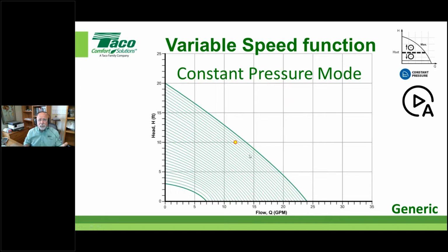The hop up is nothing more than what a standard single fixed speed application does. If you remember sitting through pump class 101, you understand as resistance increases, it goes from the right and up to the left. So that little hop is that initial feel of the zone valve closing. Then it says, hey, but I have the ability to slow back down and maintain a constant pressure, hence the name. And so watch again as we change things.